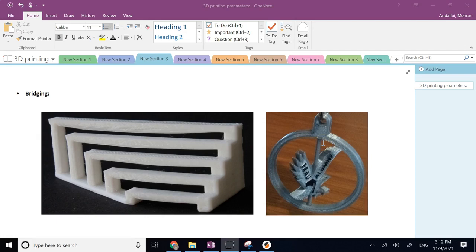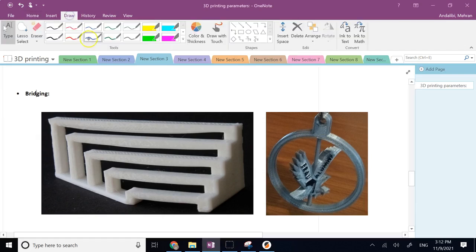If you print plastic and you print it all as one piece, as I did, then the shaft is going to be attached to the interior surface of the hole, and then you cannot achieve the rotation here. So inside this area that you can see, if you look at it, there is this hole, right?